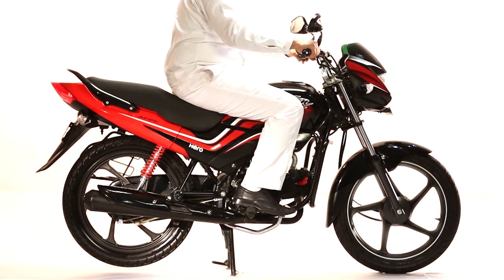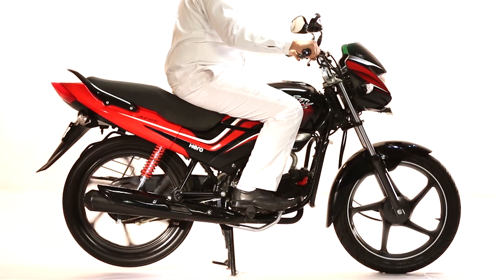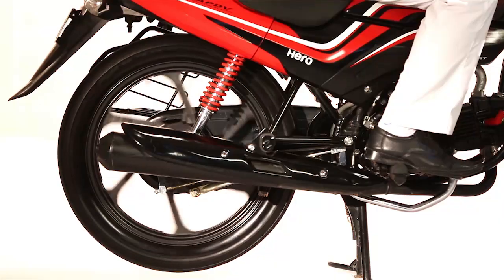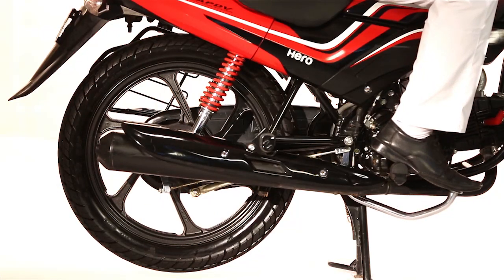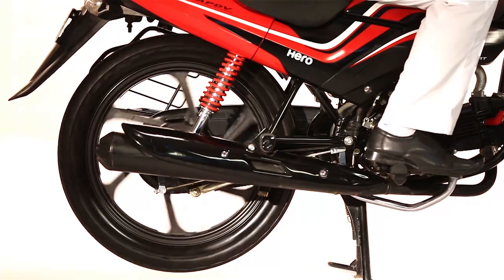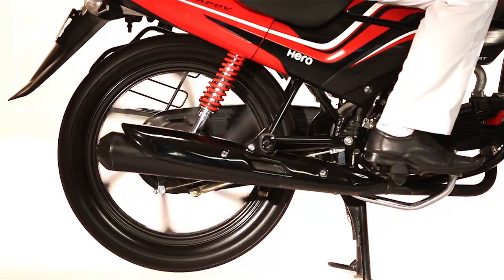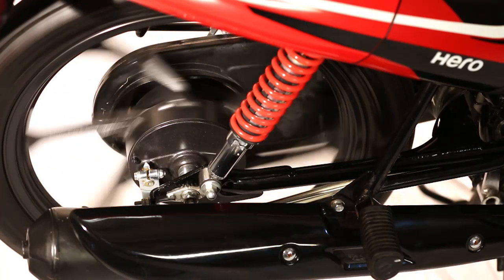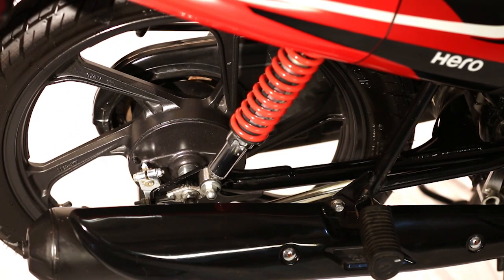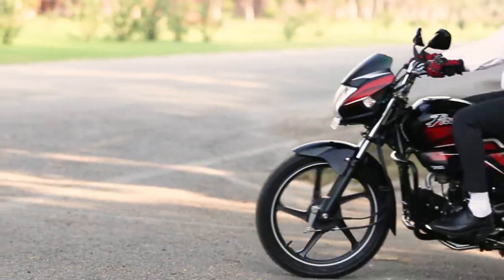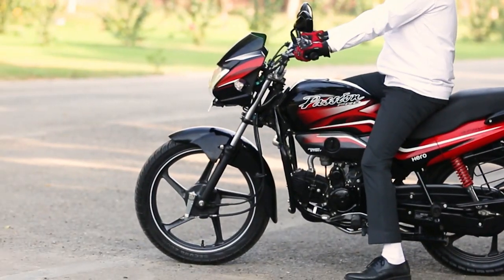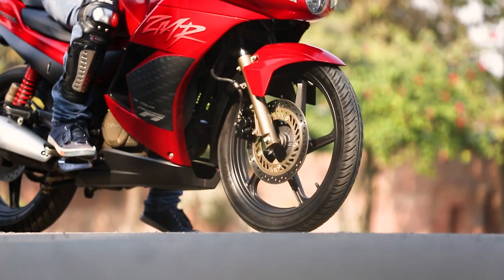When the brake is operated, the force that works to stop wheel rotation, that is, braking torque, is generated. When the wheel's rotational speed is decreased by this braking torque, frictional force is generated between the road surface and the tires of the motorcycle, which have forward inertia. This frictional force works as a braking force which decelerates and stops the motorcycle.